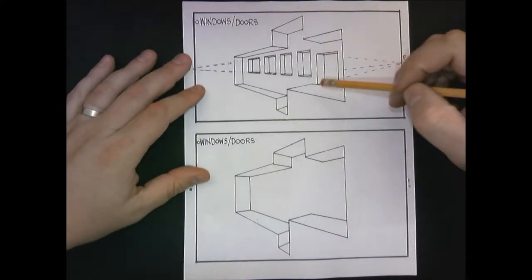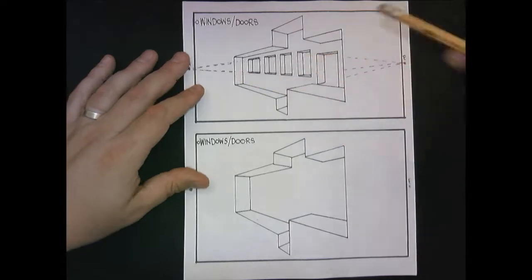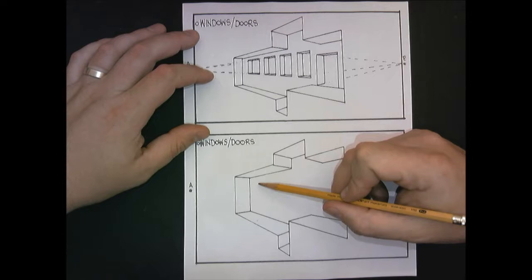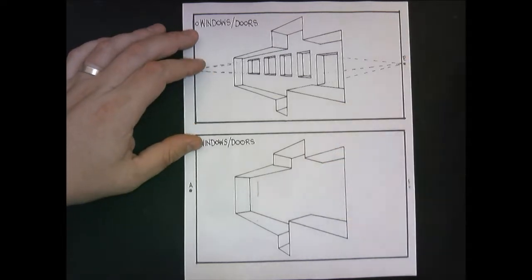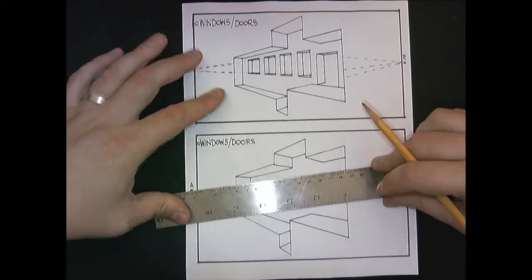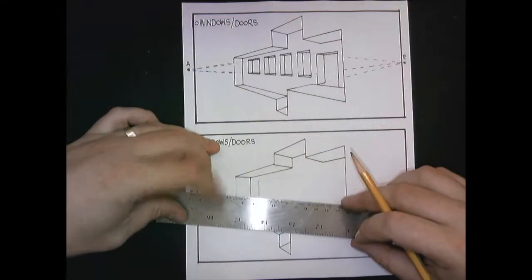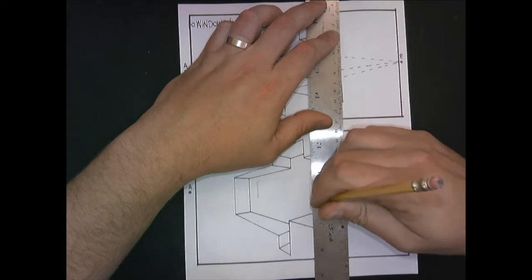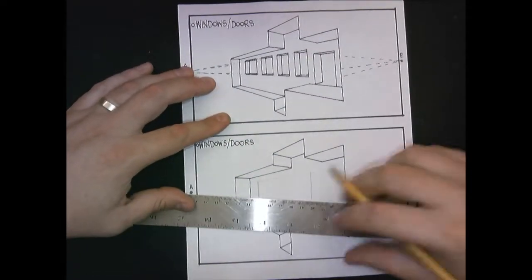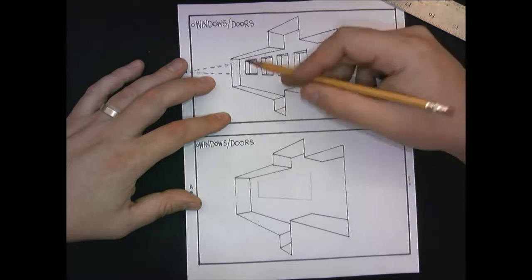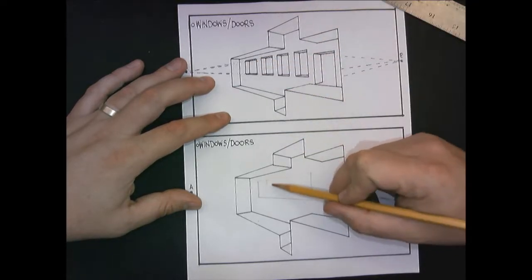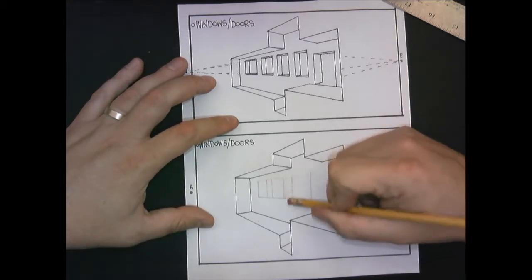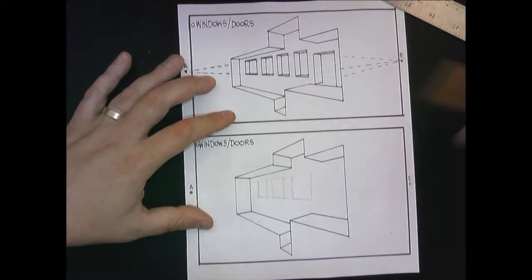Alright, windows and doors. How can we create windows and doors inside of an indent or an opening? Real simple. We start with an initial vertical line, and I'm going to line my ruler up back to point A, and I'm just kind of trying to draw the span of the windows. So this is like a large rectangle here, and then I'm going to divide this section up into my windows. So I've got a line and then a space, a line, and then another space here. I'm going to erase the lines in between. So now we have 3 windows.